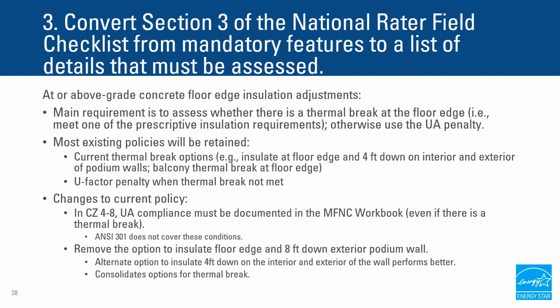We will require the envelope UA to be documented in the workbook, even if there is a thermal break, if these concrete edges exist in the building. That's because this information is not documented in the ERI model. Previously we only required it when you took the UA penalty, but now we'll require it even if you are providing the thermal break.